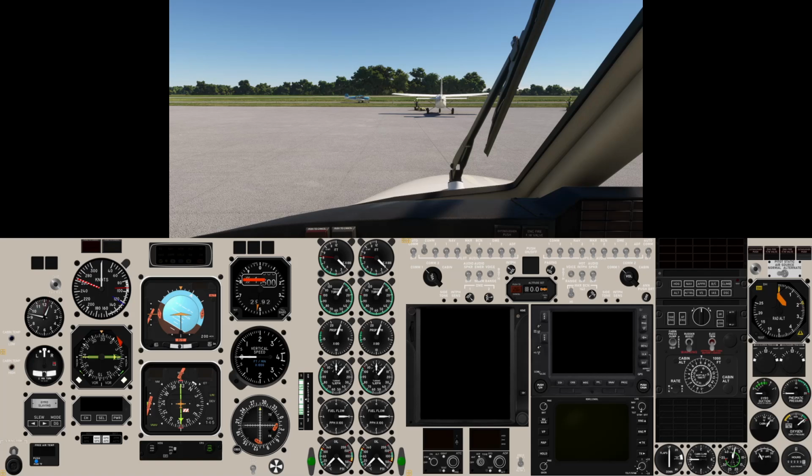The lower panel is more of an autopilot on/off, engage the yaw damper or not, and a couple of other little modes, the up/down selection for say your VS modes, etc. And then there's a little turn wheel in the middle there. Below that, the last little instrument in that stack is the cabin pressurization panel. So you've got your dump switch. There's also, not really related to cabin pressurization but on that panel, rudder boost and electric trim enable switches, and then the pressurization controls themselves, the altitude selection knob, the rate knob, etc.